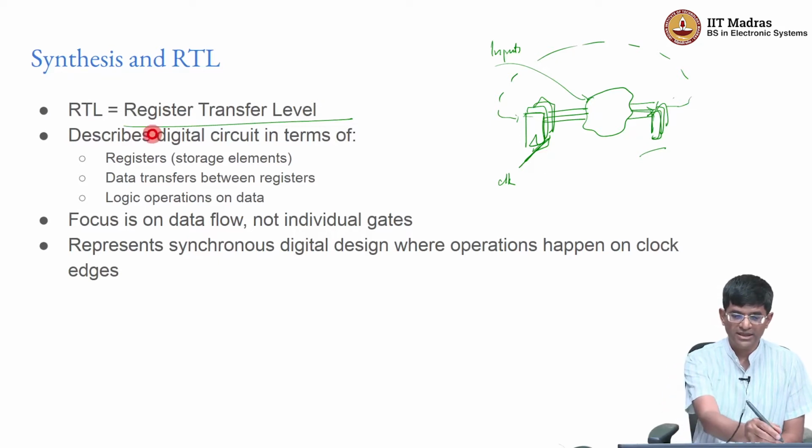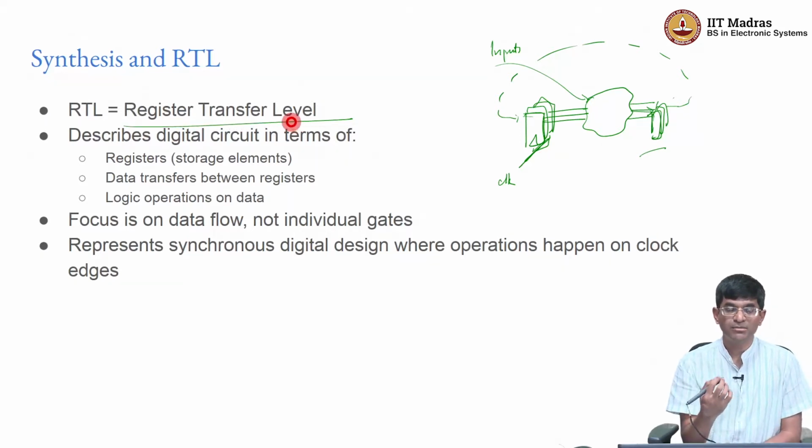Okay. So register transfer is a very important concept. It is also a slightly tricky concept because there are lots of instances where you just write Verilog code and people tend to think of it as, okay, this is the RTL. People almost use the word RTL interchangeably with Verilog. That's not the case. There is a lot of Verilog you can write which is not RTL.